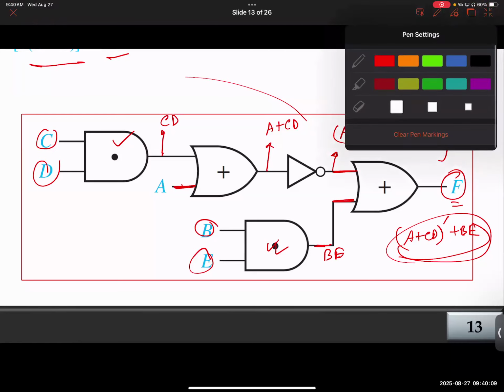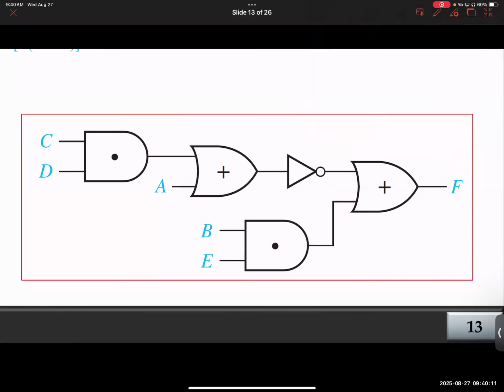So you see that we just did reverse engineering. As a quick tangent, to avoid reverse engineering, people often incorporate dummy gates. They add more gates than there is need for, and insert them in a way that doesn't change the logic function but confuses the reverse engineers, so that you cannot figure out and copy whatever Intel or Samsung is making.